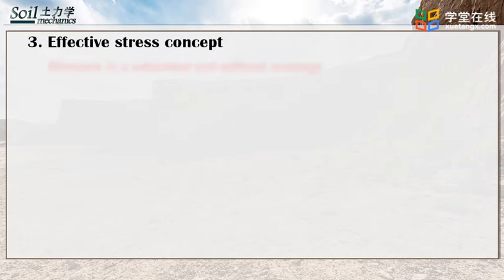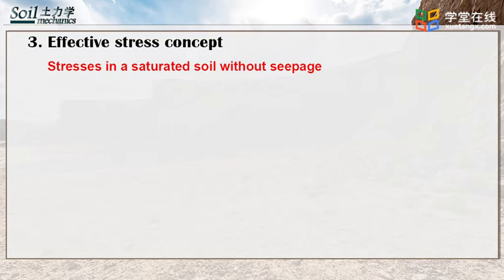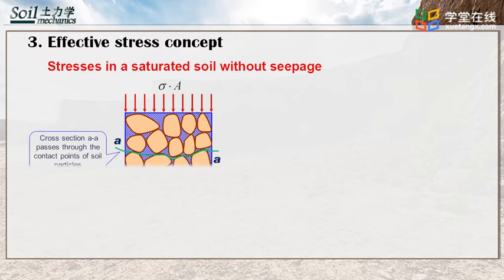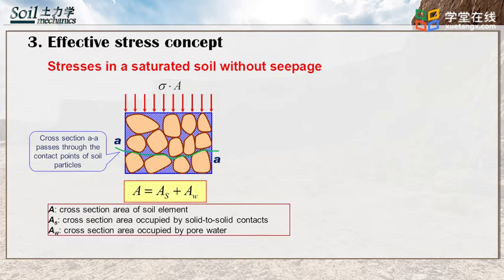In soil mechanics, the effective stress concept is very important for strength and deformation related problems. The figure on the left side shows the column of saturated soil mass with no seepage in any direction. The total force, σ times A, can be divided into two parts as presented in equation 1. A portion is carried by water in the continuous void space, u times the area of water. The rest of the total stress is carried by the soil solid at the points of contact, P_sv.